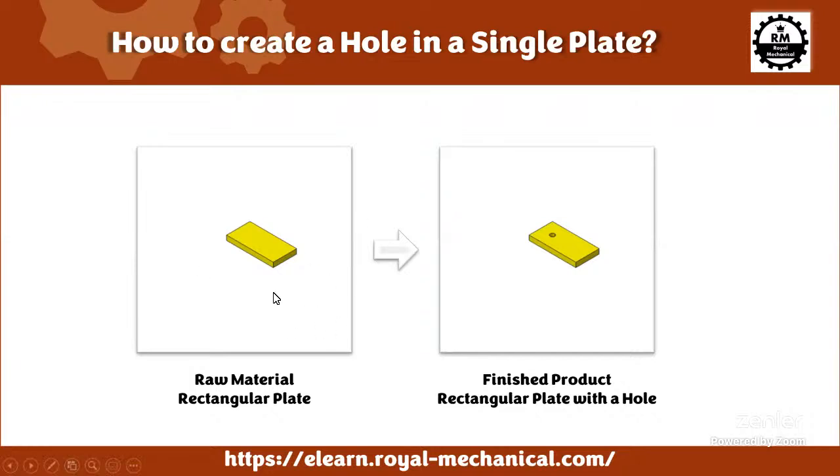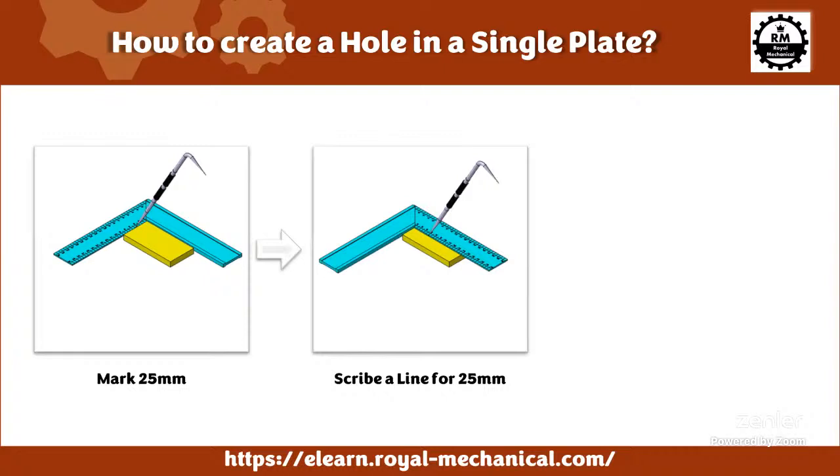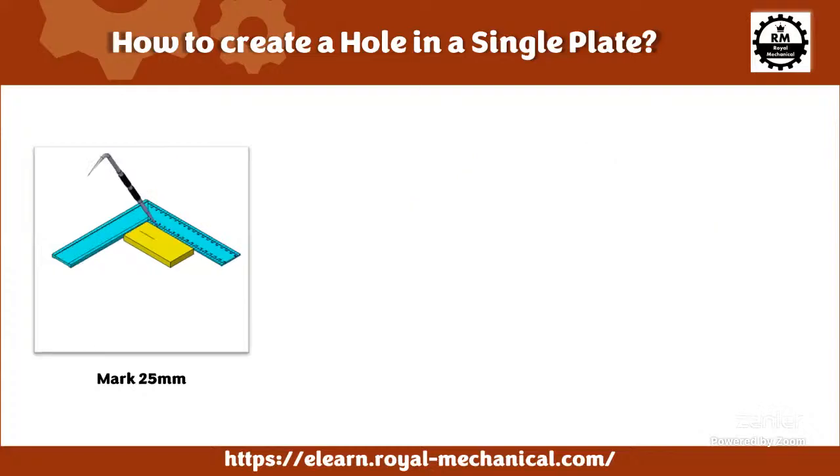So to start with, we have this raw material, which is a rectangular plate, and this will be the finished product. Let us look at how we can do it in the kind of environment, probably, that you had in your simple mechanical workshop when you did your engineering in college. You will take the raw material, use a scriber and a tri-square, and mark 25 mm from one of the edges, and then scribe a line. You will get a vertical scribed line at a distance of 25 mm from one of the edges.